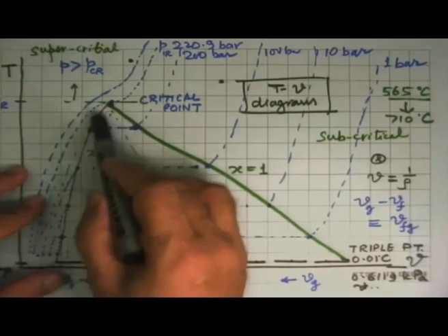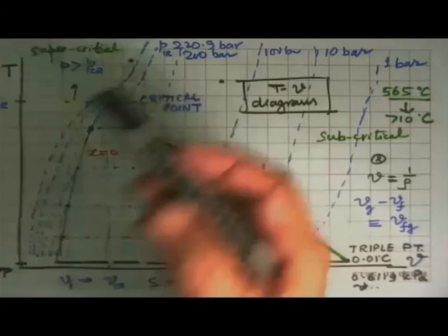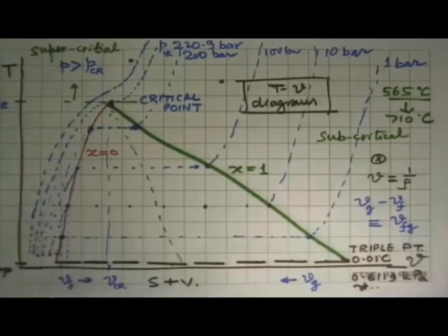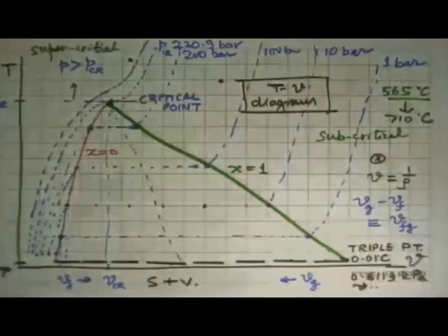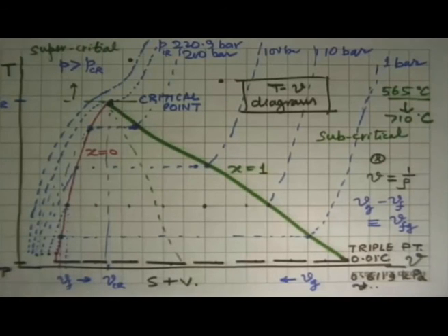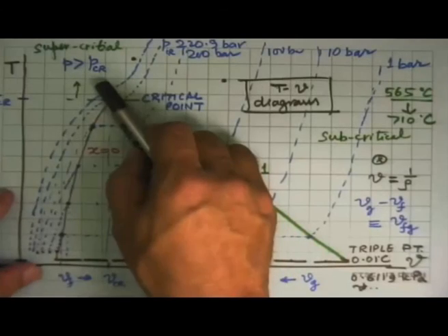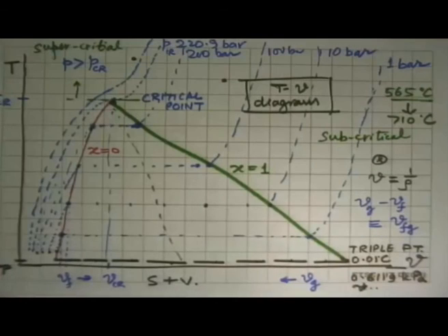It continuously shows a behavior of one type only, where the intermolecular spacing is now fairly tight and very close, and it doesn't show that it has any ability to become a vapor by getting the molecules very far apart. So that's why this thing happens here. And of course, if pressures are more than the critical point pressure, there is absolutely no hope, because now you have compressed it so much, molecules are so close to one another, they have no chance to get away from each other.